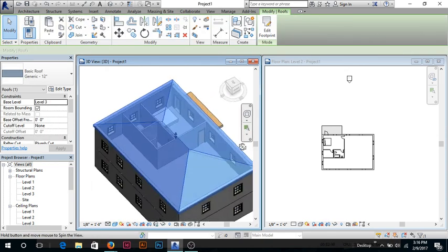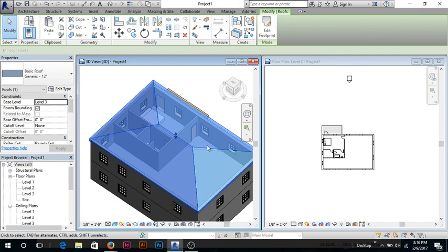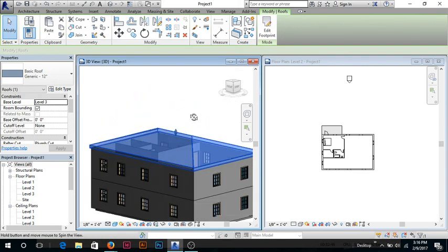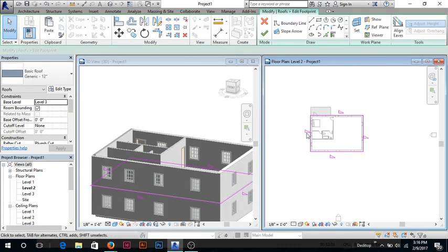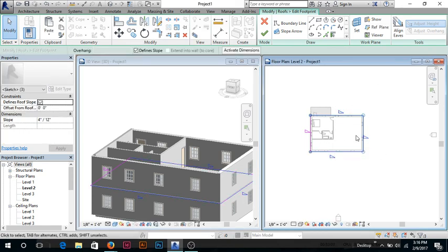So for me, in a lot of my designs and a lot of my studio work, I like to slope roofs like kind of modern contemporary homes, basically. So if I go to edit footprint and I say, okay, I want the building roof to slope from this side to this side only, so only slopes up. I can just simply highlight these 3 lines, these 3, basically the beginning of the roofs, and I just go define slope, and I say, okay, I'm gonna click on this one.